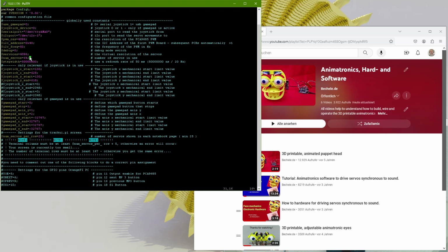frequency of 100 kilohertz, which is the standard. So you need a certain speed. There's a certain time you have, and if you have a number of servos, each servo needs some time to be set on the chip. If you exceed this number and the repeating frequency is too high, then of course you cannot serve all the servos.